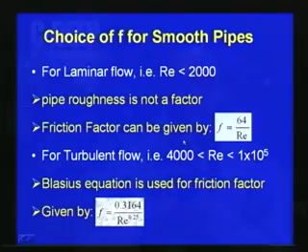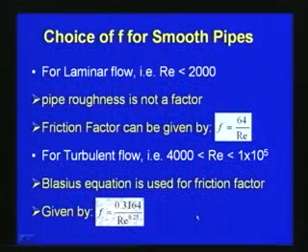So, like this, for various conditions based upon various experiments and some empirical relationships, the friction factor has been calculated for various kinds of pipe flow, for various pipe materials and roughness factors. As far as laminar flow is concerned, we can directly get the friction factor F is equal to 64 by Re, and as far as turbulent flow is considered, Blasius has shown through experiments that F is equal to 0.3164 by Re to the power 0.25, but for other ranges various equations are available. We will be discussing in detail this friction factor and the various relationships available in the literature.